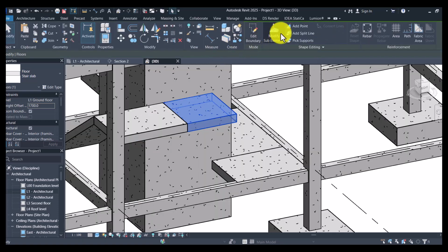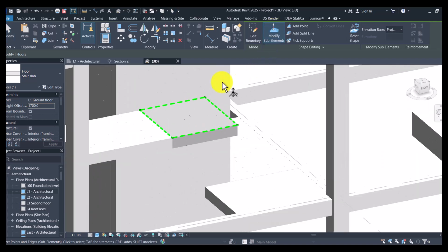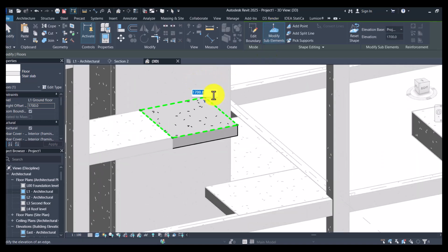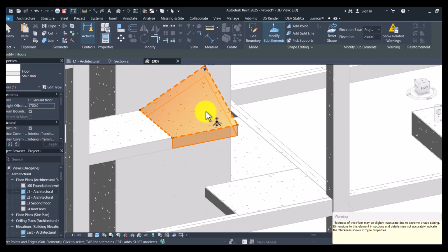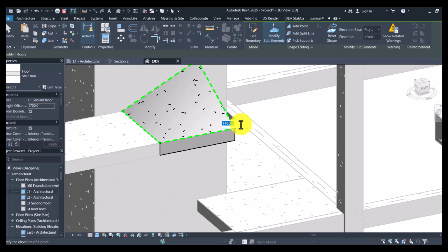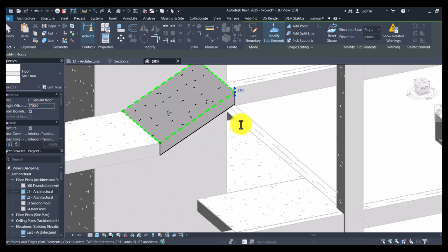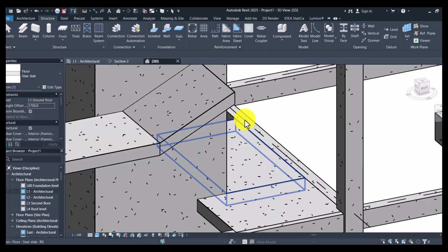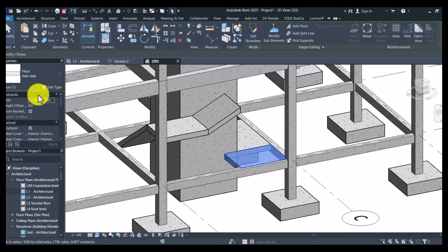So I'm going to add 600 to this. So I'll say this plus 600. I'll put an equal sign behind here. And so this is 2300. There we go. So I'll get the next landing. I'll put it at an offset of 2300. See how it's coming.